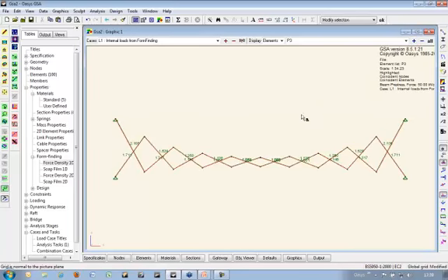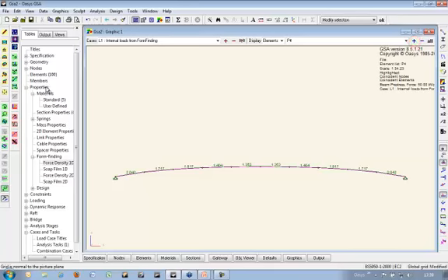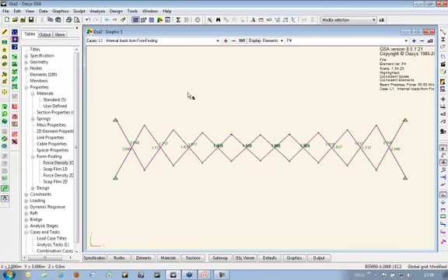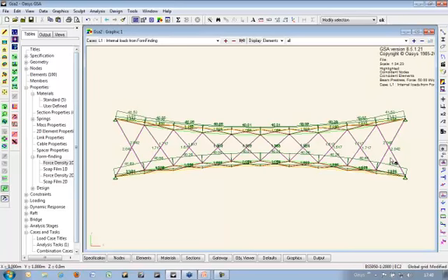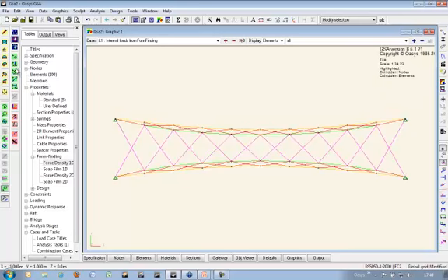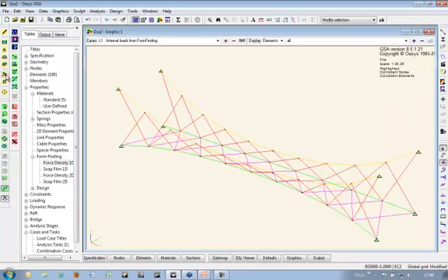The verticals, you see, they're quite short in the middle, so we're getting about, you can read that, 1 kilonewton in the middle. End cables about twice as long, twice as much pre-stress, and the plan ones, again, about 1.34 up to about 2 kilonewtons pre-stress at the end. And then, of course, with this in place, we can now load this and analyze it, and so on.